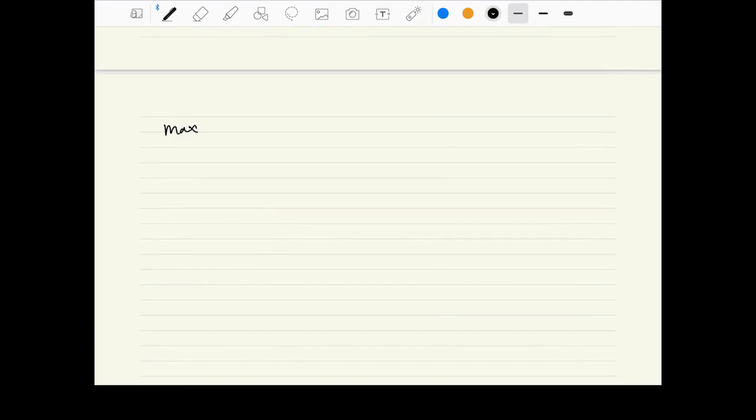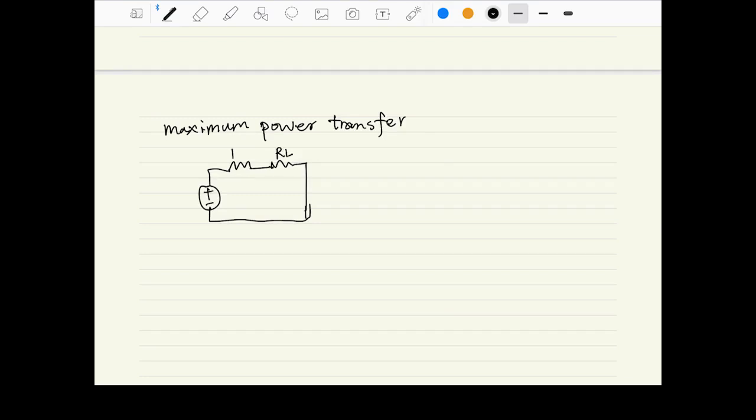And one last thing is an extension for that: maximum power transfer. In the lecture, we computed the equivalent circuits with a load. And our conclusion is that when RT equals RL, PL is maximized, right? But the thing we need to be careful about is that even when it is reaching its highest value, we can see that half of the value is wasted on RT.